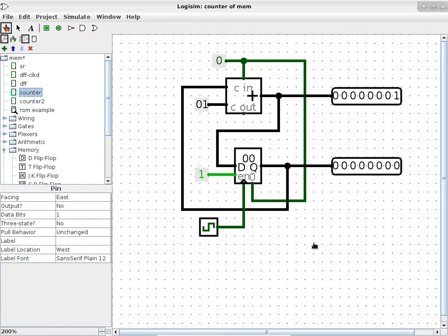So when you look at this, the register is right here, which is kind of what we talked about, except now we look at the entire register as one single device instead of breaking it up into 8 individual D flip-flops. So we have got the enable. The enable is always a 1 because this is the only register in this entire system. There's no reason why we cannot enable it all the time. The clock line is controlling when we want it to update.